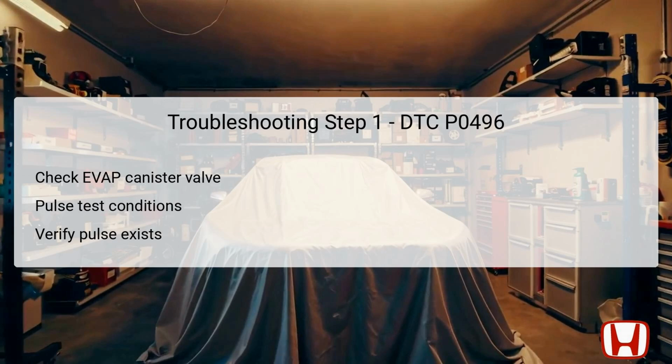It's critical to see a consistent pulse, as this indicates that the valve is operating properly. If a pulse does not exist, it may suggest that the purge valve is stuck open, which is a leading cause of the P0496 code.